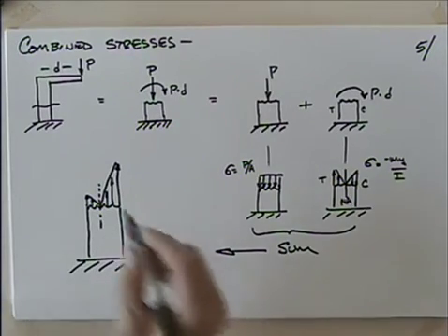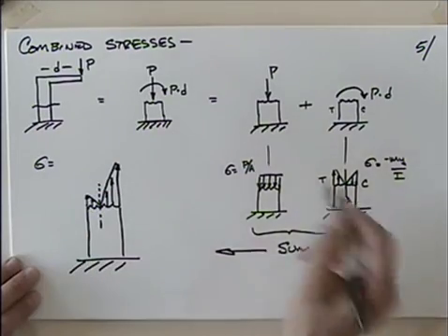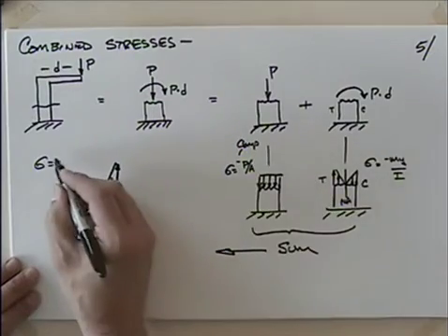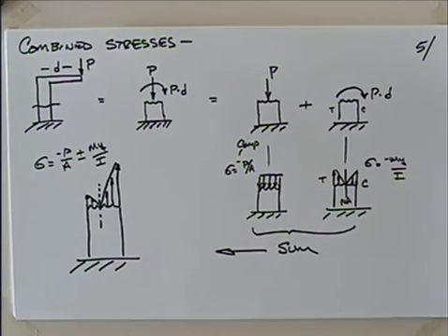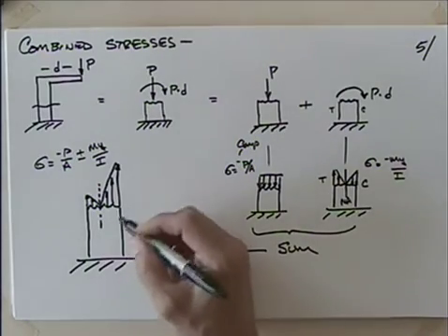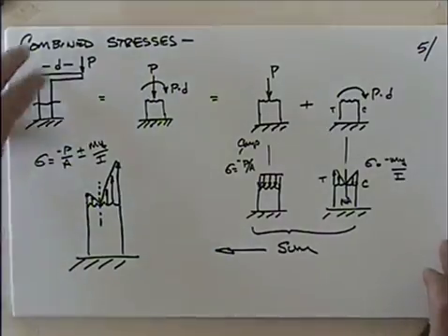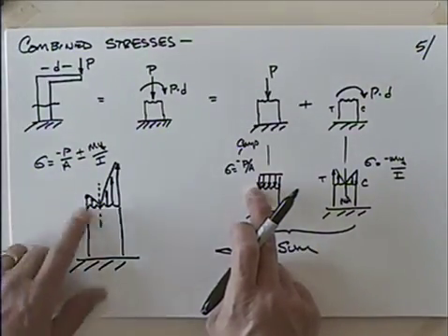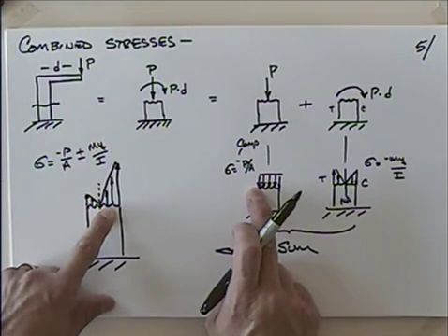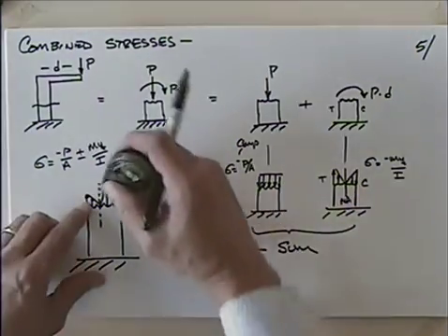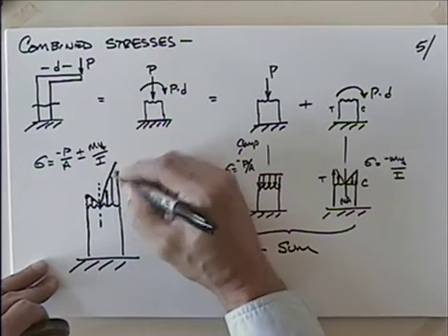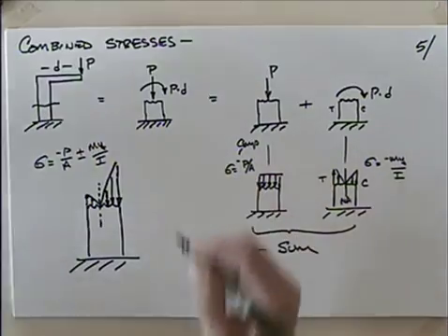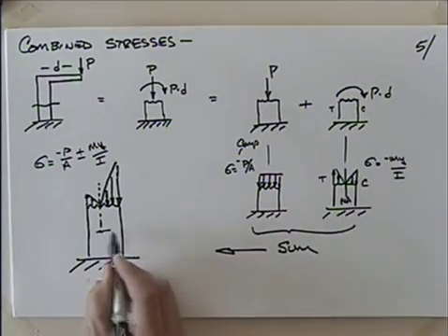We shifted the neutral axis. And we can talk about the stress here, sigma, being equal to, and maybe we should say minus P over A because it's compressive. So minus P over A plus or minus My over I, right? Oh yeah, I've drawn this the wrong way, haven't I? I've got tension and compression, so I should have a small amount of tension, and these need to go the other way because I've got a lot of compression. Is that what you're asking? My arrows are the wrong way? Yeah. Now I think we're okay. And effectively I have moved the neutral axis.